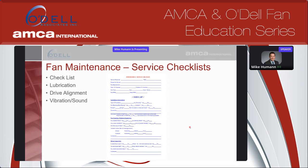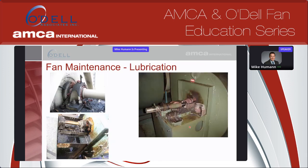Most fan manufacturers, and a lot of companies, have their own service checklists and maintenance lists. It's really important to have that as a baseline, and it's a nice tool to follow along to make sure you don't miss anything, and to take everything into consideration when you're first looking at a fan. That checklist includes wheel inspection. Is the wheel clean? Does it need to be cleaned more often? There are certainly a lot of little things in there that you can account for and watch, so you can help maintain the longevity of the fan and hopefully live out its service life.